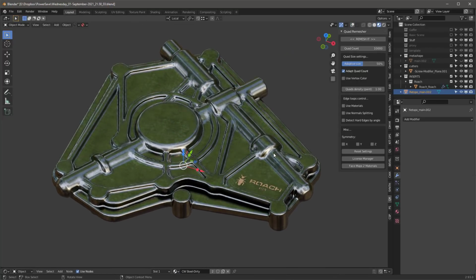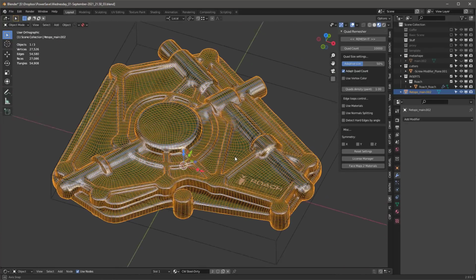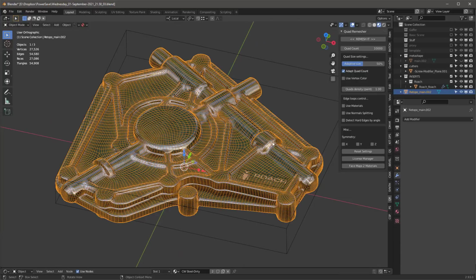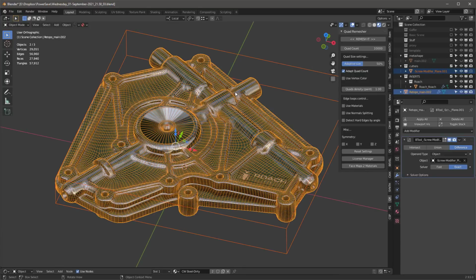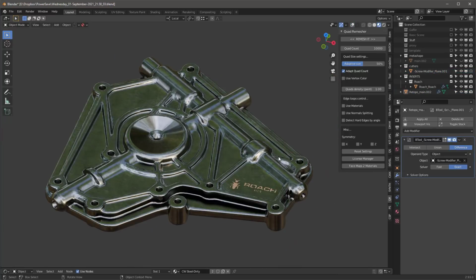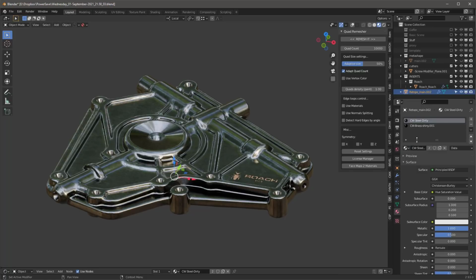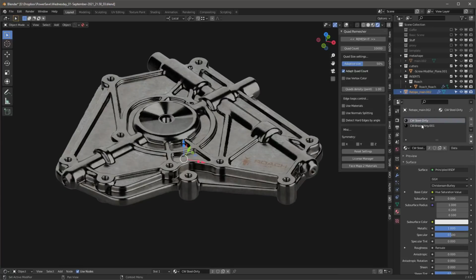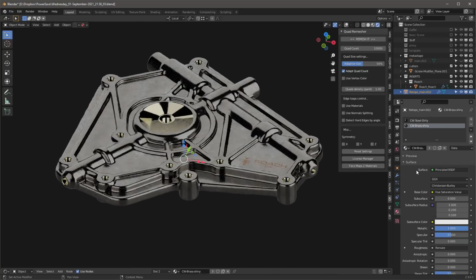So now I've got it down to 27,000 faces, which is actually good for a model this complex. So next, I'll select this, and then this, and Control minus, and let's get our Boolean subtraction added to this. Turn off this, and you can see that's what that did. And if I look at this material, you'll see I still have the brass shiny, but it's got this brass shiny 1 because that's what the quad remesher added. So I need to go back in and just add this brass shiny on it.